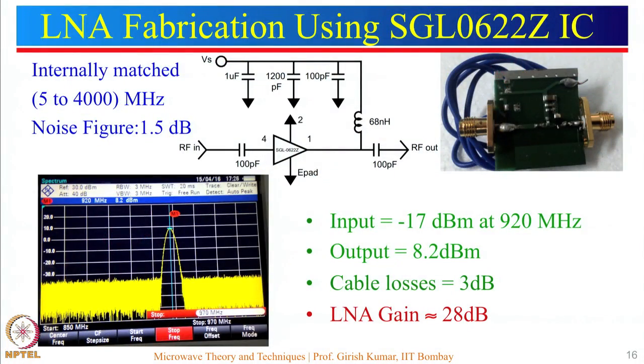Of course, the next stage one can optimize for maximum gain, because that stage's noise will be divided by this very high gain. So, even a poor noise figure of the second stage will not add to the overall noise figure, because the gain of this particular stage is very high.